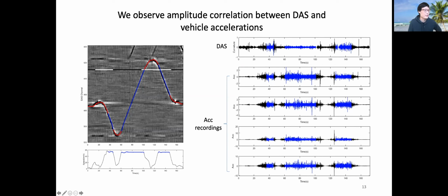It is basically a second derivative in time of the raw strain recordings. We are looking at a dynamic response, not quasi-static. Below are the car's acceleration recordings from the accelerometers installed at the 4 wheels, so we have 4 of them. We see that these two types of recording have some signatures in common. For example, we see amplitude jumps in all of the sensors. These jumps can be related to bad road condition.